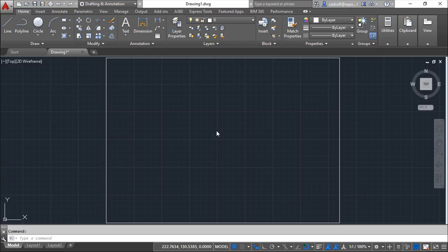Regarding polylines and splines, the advantage of using polylines for curves is that these polylines can be changed in many different ways, and splines are a little more special. Anyway, sometimes you may need a more exact representation of a curve, and then you should use a spline. The spline objects are true non-uniform rational B-splines, or NURBS.